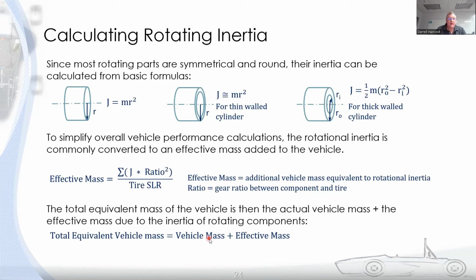You might be a little bit off, especially if you're in a very large radius turn and you are accelerating relatively hard. You could probably even proportion it, right, for how much longitudinal acceleration you're using versus how much lateral acceleration. Something kind of like a friction circle approach.